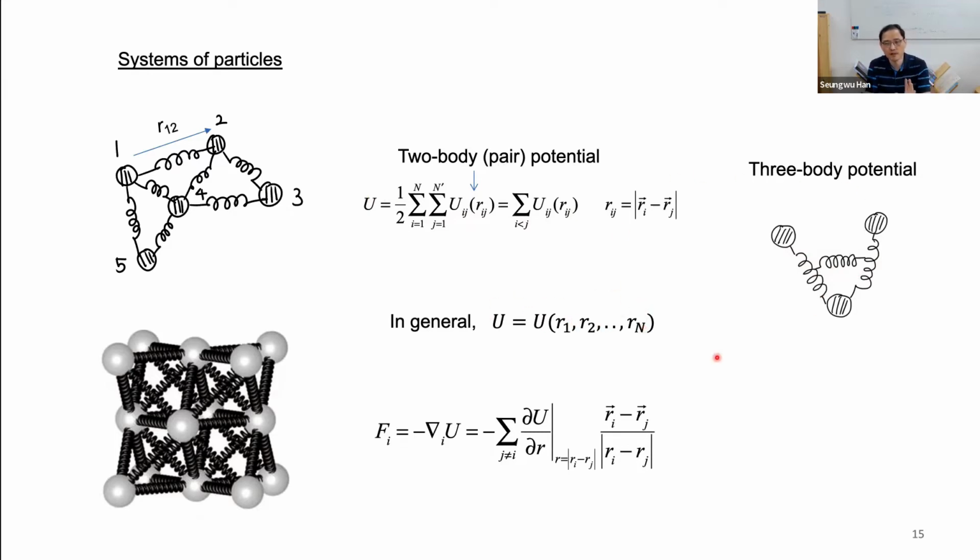So there are many different types of potential, and in order to get the force, we take the derivative, or the gradient, of the potential. It gives you the force that a certain atom feels at a certain moment. Okay, and using that force, we can simulate material evolution.